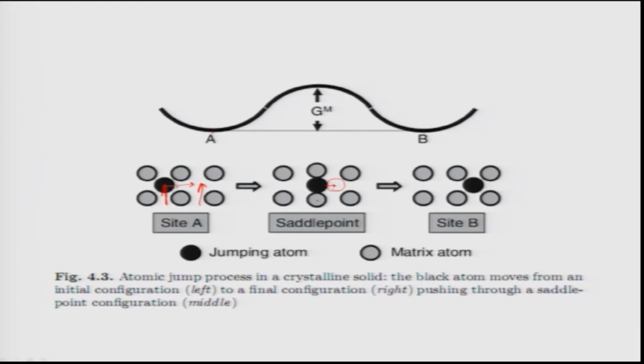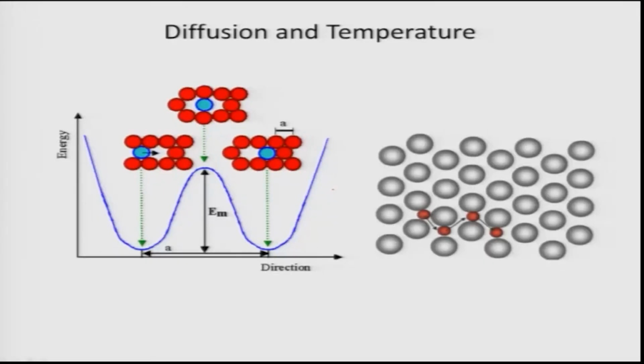So, this has to be a thermally driven process. If thermal energy sufficient for this is not provided, the atom at the central position here cannot move to the next position, or rather diffusion cannot happen. This is why the diffusivity must be dependent on temperature. So, a simple analogy tells you that. Now, how can we make it very clear? This is why I have taken some slides from the internet, and I am explaining in a more detailed manner. Three different configurations are shown nicely here.